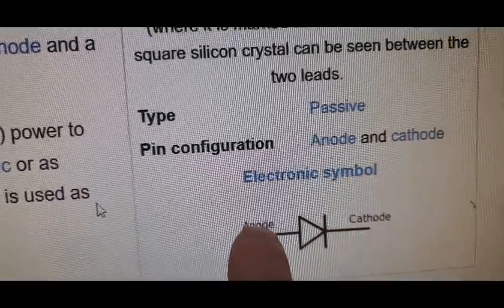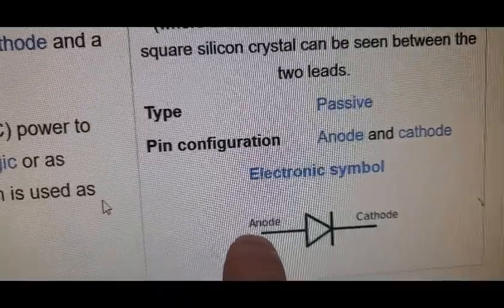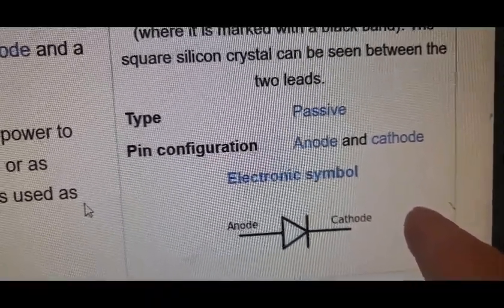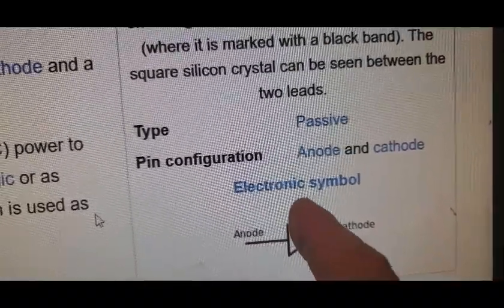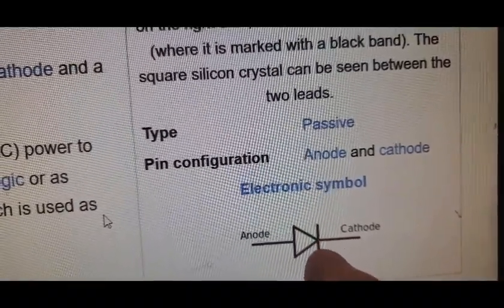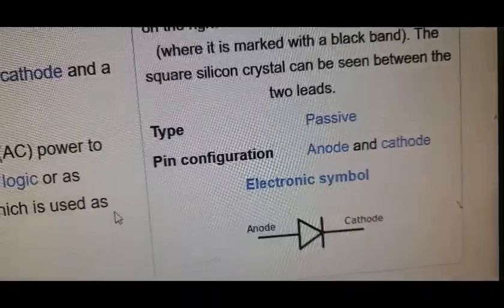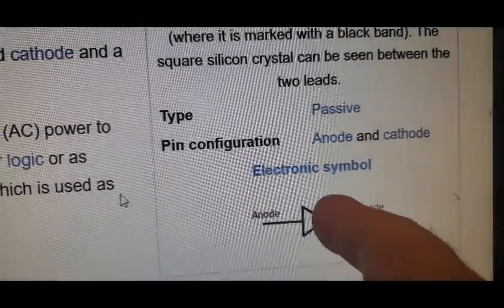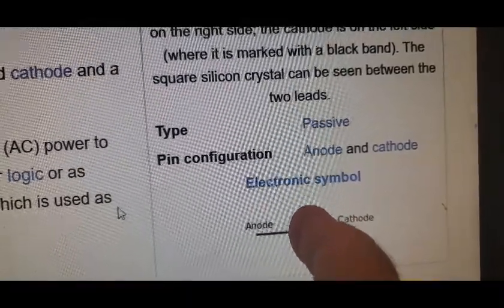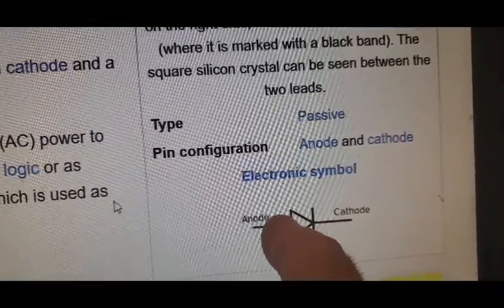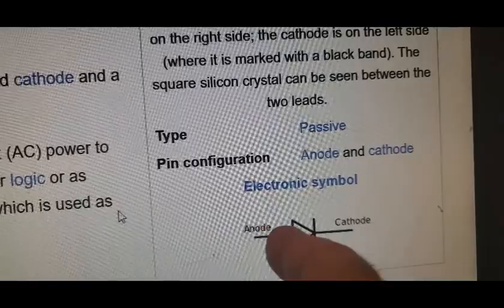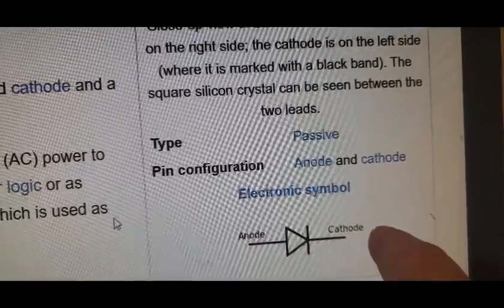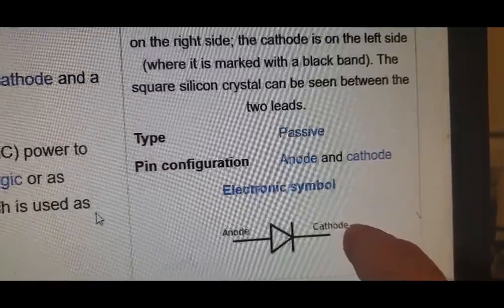This tells you that you can go from positive to negative that way, and there is not a lot of resistance. There's a voltage drop, but for a silicon rectifying diode you need about 0.5 to 0.6 volts, and then it opens the floodgates. Now it will pass through with resistance almost like a straight line wire.